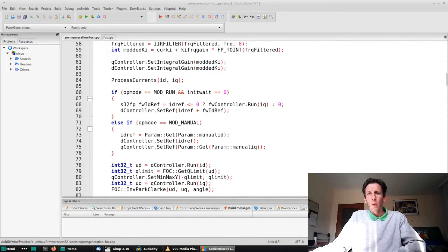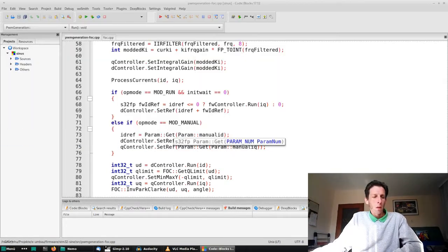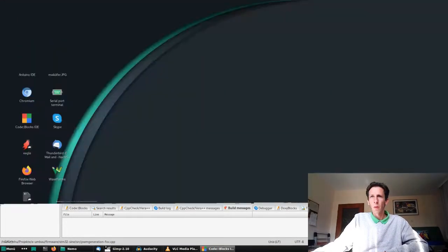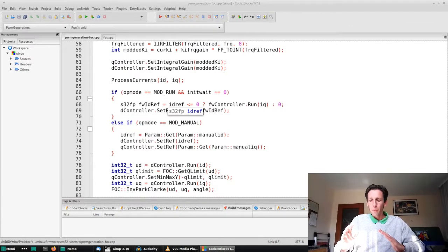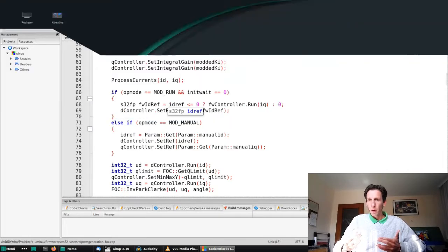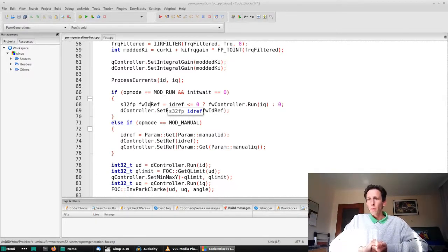Okay, and then we have another practical detail, which is field weakening. Obviously at some point the PI controllers will run out of voltage to maintain the requested quadrature current. So what we do in this case is weaken the rotor magnetic field, and thereby we reduce the back EMF, the voltage that is generated by the spinning rotor, and thereby we generate more room for quadrature current.